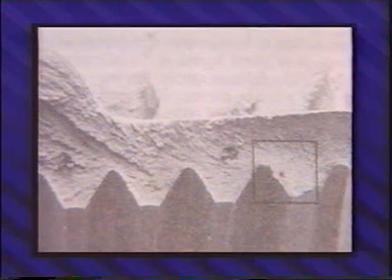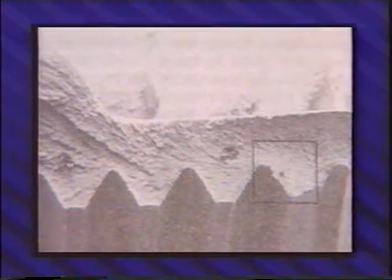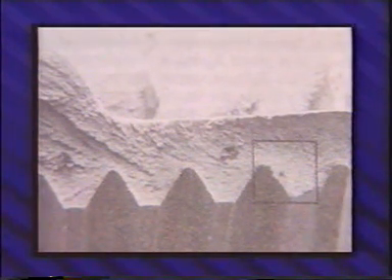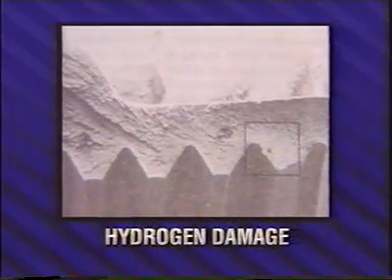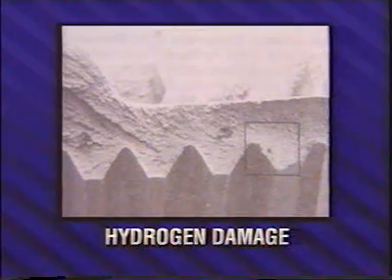Plating is usually detrimental to the fatigue strength of plated parts. Carbon and low alloy steels, particularly steels of high hardness, are susceptible to hydrogen damage. The hydrogen is absorbed during the plating cycle and the associated acid cleaning cycles. Hard plating materials, such as chromium, are usually in a state of residual tensile stress after being deposited on the base metal. Cracks develop in the plating material. The cracks act as stress raisers, and if the cyclic stress amplitude is sufficient, the stress raisers may produce cracking in the base metal.